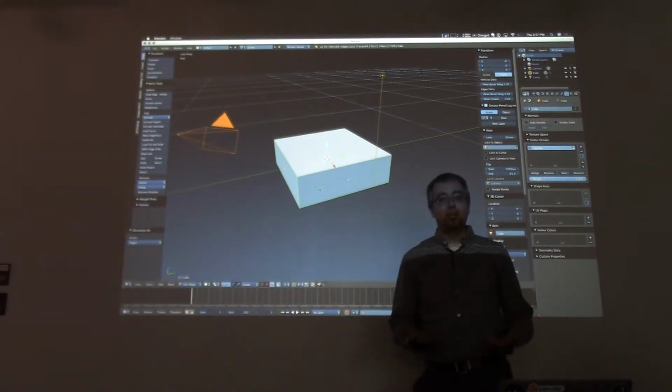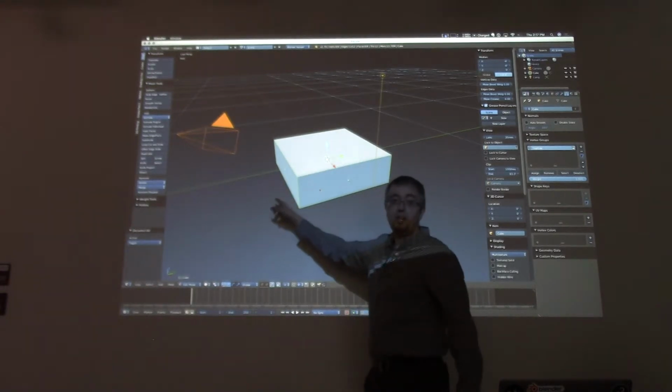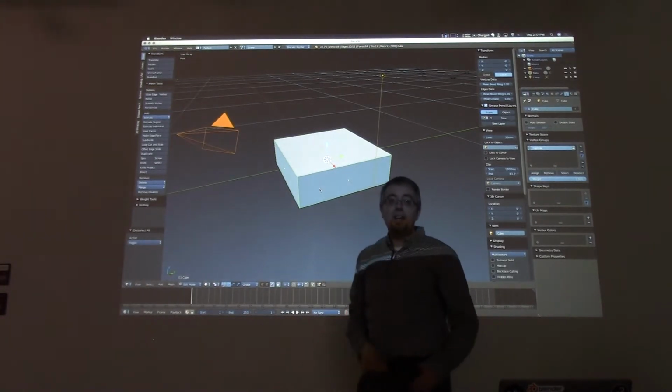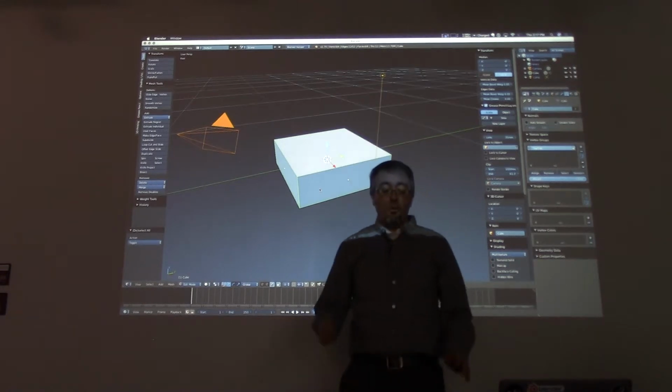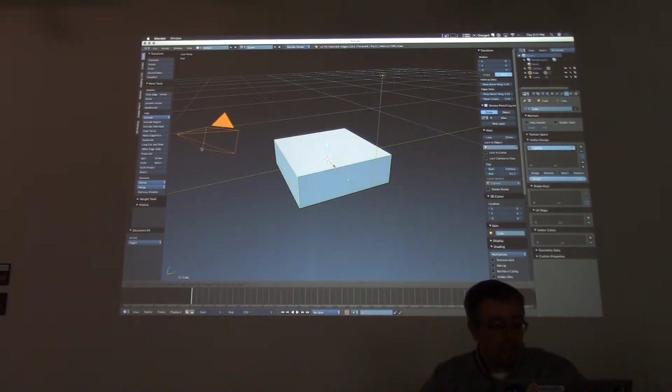Basically, this is a loop cutting tool which will cut all the way around the object in a particular direction, and we can actually make multiples of these. Watch how I do this. This is weird. So I'm going to hit Loop Cut and Slide. And I'm going to come back over here, and you'll see that it's automatically finding different directions of loops. So there's a loop direction that goes around the box this way, around the box this way, and we can